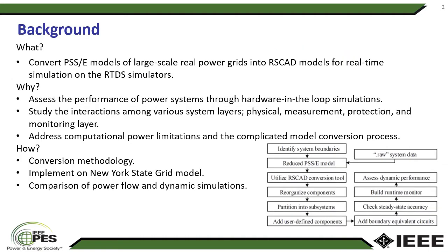So in this specific paper, we're going to focus on converting PSS models of large-scale real power grids into RSCAD models, specifically for real-time simulations on the RTDS simulators. We need that for several reasons. First, this will help us to assess the performance of our system through hardware-in-the-loop simulations. Second, this study will help us to understand the interactions among various system layers such as physical, measurement, and monitoring layers, which will help us in cyber-physical energy system studies. And third is to address the computational power limitations of RTDS, specifically through this complicated model conversion process.